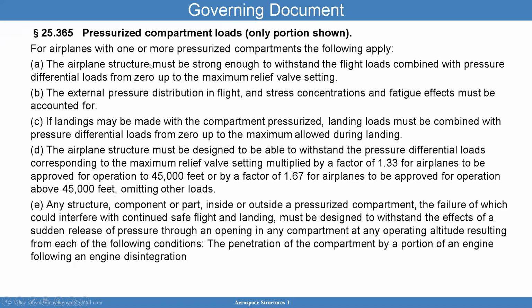The airplane has to be strong enough to withstand the flight loads combined with pressure differential loads from zero up to the maximum relief valve setting. The external pressure in flight and stress concentrations and fatigue have to be accounted for, like those from a window. If landings may be made with the compartment pressurized, landing loads must be combined with the pressure loads. That makes sense. You want to combine all the loads to get the worst case scenario.